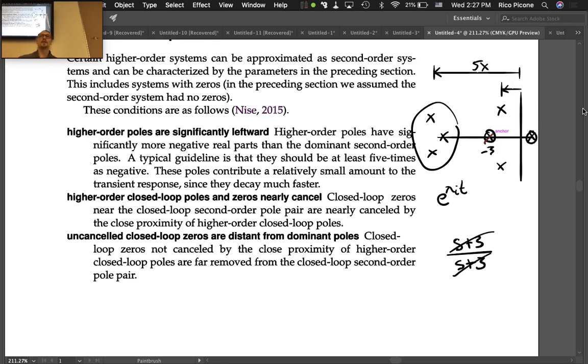And you put a 0 on it, it does cancel, and in terms of forced response, technically, it will be stable. However, if there's any disturbance in your system from equilibrium in that modal direction, the system will still go off to infinity. So it's still unstable even if you have pole zero cancellation of an unstable pole.